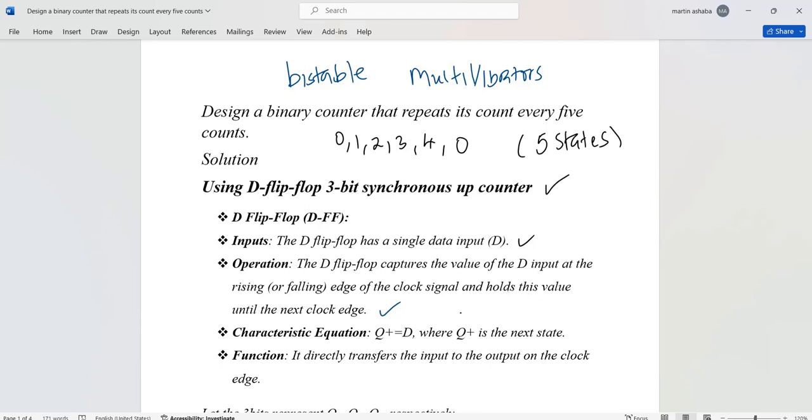It can stay in 0, for example, until changed by another external source, or until changed by another triggering mechanism, for example, by using a clock signal. So until you change the state or apply an external source, it will remain in logic 0. Now, when you apply an external source, it will again go to logic 1, and in that logic 1, it will be stable. So that's why we call it a bistable multivibrator, because it is stable in two states.